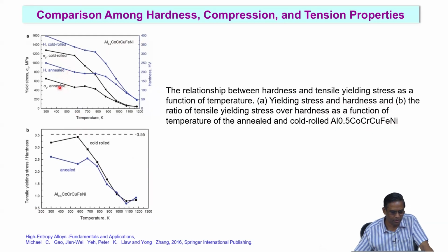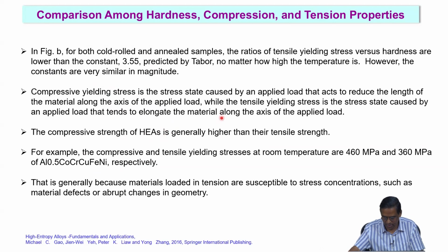So, the transition of this yield strength after annealing is not drastic with temperature as compared to the hot rolled or cold rolled conditions, and you can also relate that with the hardness changes. Yeah, they are all very conventional ideas.